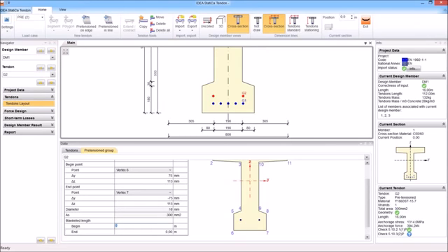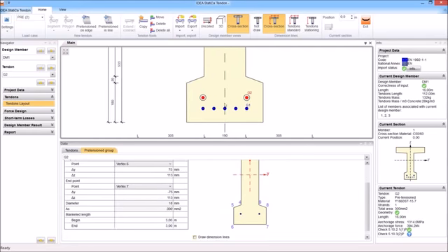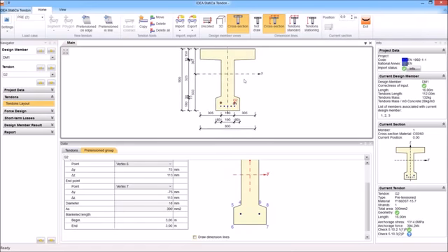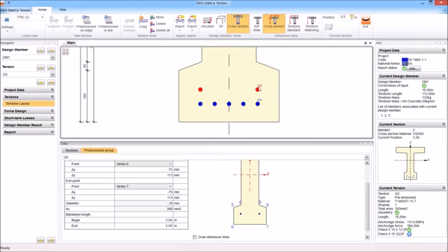As we need to reduce the pre-stressing force at the beginning and at the end of the beam, we define a blanketed length in which we have debonded strands, 3 meters. So now you see that the tendons or strands are debonded in position 0 here. And if we go back to this, I can show, we go to 3 meters, then it disappeared, so these debonding tubes disappeared. So that's it.